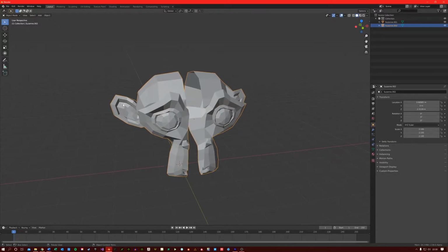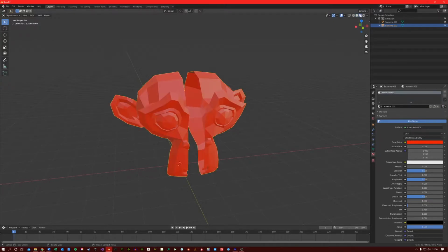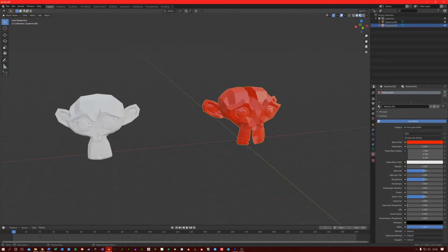I am now going to create a material for our mesh here. I also want to give this mesh the same material. There is a quicker way to assign a material to another mesh. With our material selected here, if you come to this browser icon, hold down the control button and then left mouse click drag, you can drag the material onto the mesh.